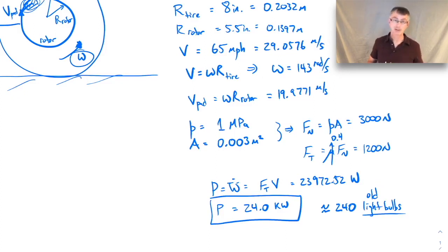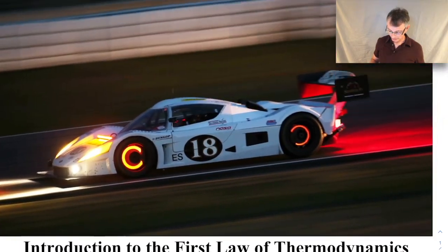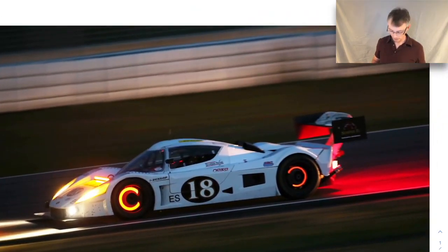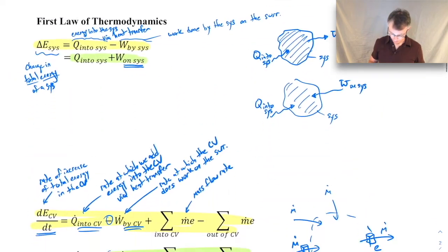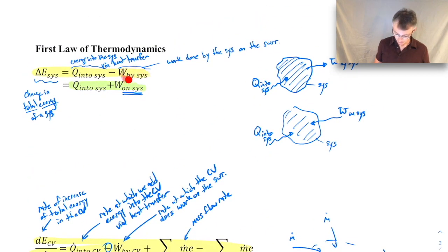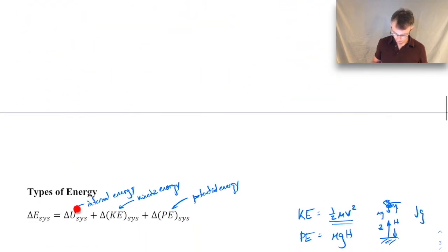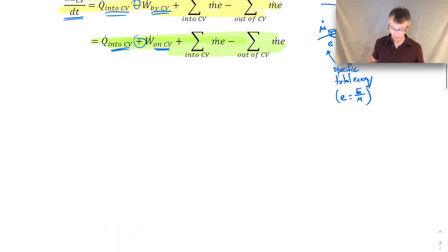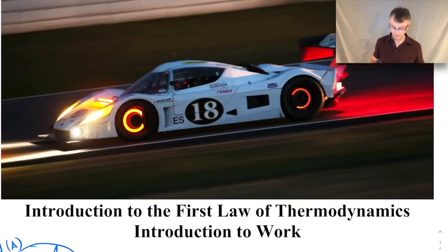So whenever you step on those brakes, you're dissipating lots and lots of energy per unit time. That's why, if you're in a high-performance vehicle and they step on the brakes really hard over time, the brakes will start to glow, because all that energy is going into that rotor and it heats it up. You can see that from the first law expression: if we're doing this work on the brake rotor, then its energy is going to increase, and much of that energy goes into the internal energy of the brake rotor, and that means its temperature goes up, and that's why it glows.